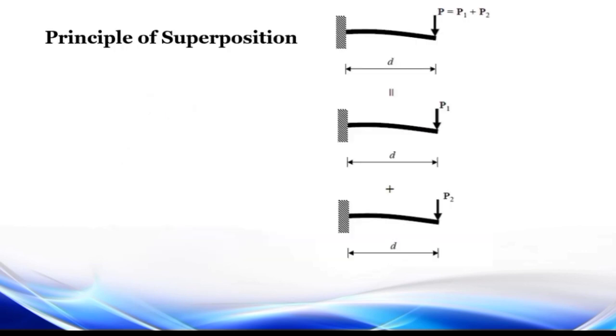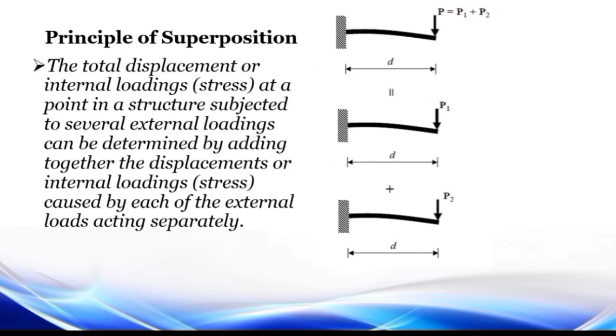So what is the principle of superposition? The total displacement or internal loading or stress at a point in a structure subjected to several external loadings can be determined by adding together the displacement or internal loadings caused by each of the external loads acting separately.